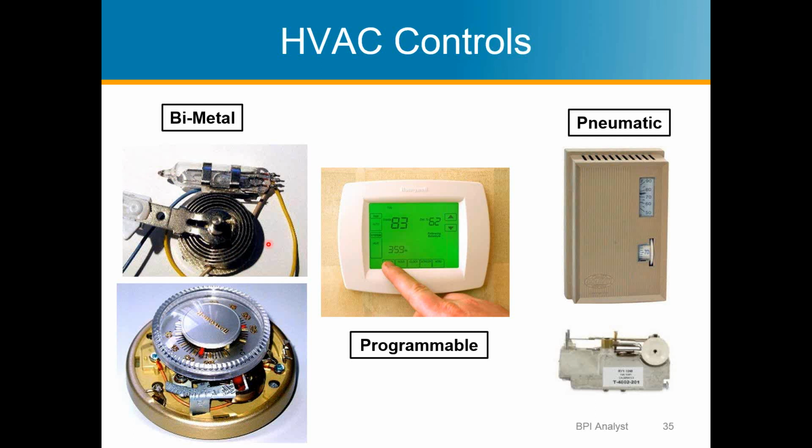You want to be really careful with mercury thermostats. You see fewer and fewer all the time, but that amount of mercury is enough to pollute a very large pond, so they should be disposed of properly. It's a hazardous material and poisonous if it gets in the water system. And so this is a bimetal strip in here. Yeah, right there's the tip of the mercury bulb, so there's mercury in there too. It could be a square one too, but I'm just showing the round one.